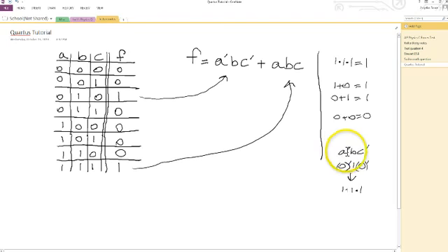The reason we picked A0, B, C0 for the combination of 0, 1, 0 was because if the combination of inputs is 0, 1, 0, then we're going to NOT the zeros so that 3 1s are ANDed together, and that returns a 1. And that would only be true for that one combination. All of the other combinations would still yield a false. And the A, B, C on the same logic would yield a true only for 1, 1, 1. Okay, so that's the expression we'd like to make. A0, B, C0, A, B, C.